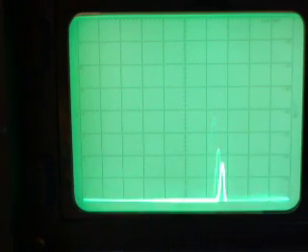And if I increase it this time, you'll see that it drops off quite sharply, then picks up again, and then starts to drop off incredibly quickly on the way down the other side. And that's about the same sort of distance the other way. So we're right back down in the noise over here again now. So we're 2 kilohertz above the center frequency.